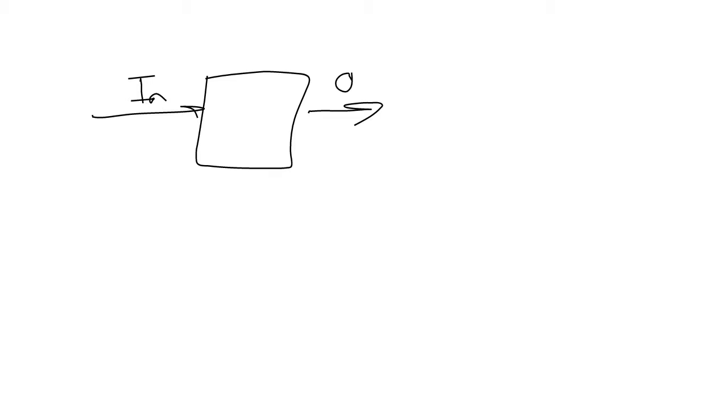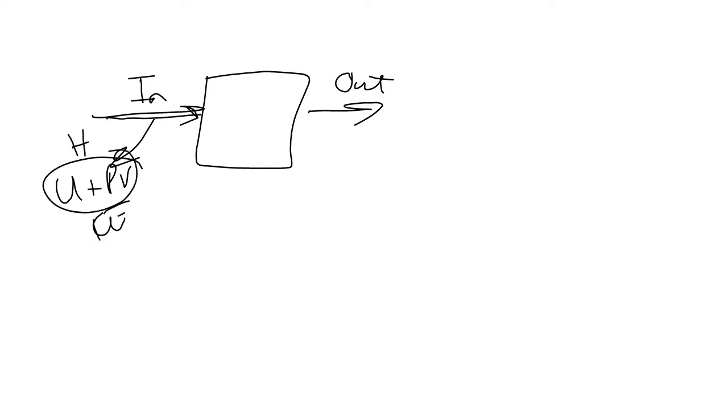So if I now, I hate this eraser. If I now want to do that energy balance again, and I've got streams flowing in and I've got streams flowing out. Remember, what does the stream bring with it? What energy packets, if I take you back to your second year, first lecture or second lecture, somewhere there. It's got its internal energy, it's got the PV part that is in order to force it to flow, and that is its enthalpy. It brings with it its kinetic energy and its potential energy. The stuff going out takes with it those same energy components, kinetic energy and potential energy.